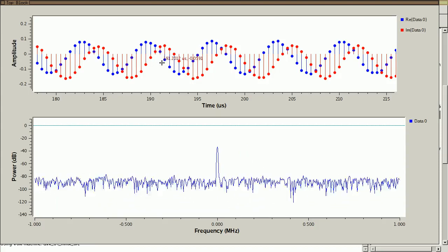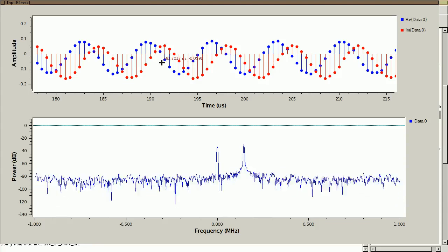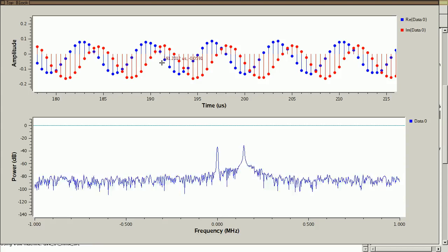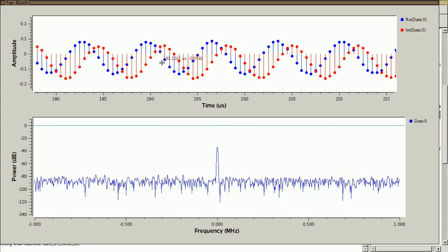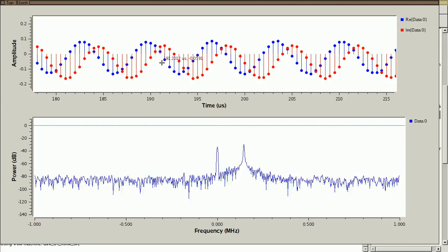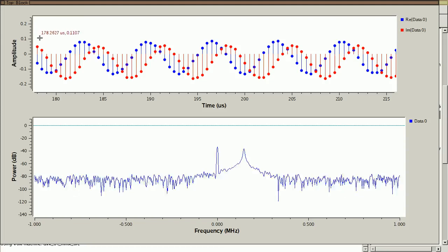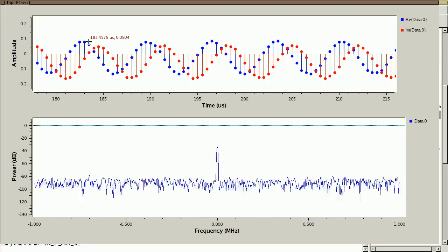That's the scale that we expect, because when the Osmocom source receives information from the HackRF, it takes these 8-bit values and then scales them and assigns them floating point values that are between negative 1 and 1. In other words, we're using a very small portion of our dynamic range.